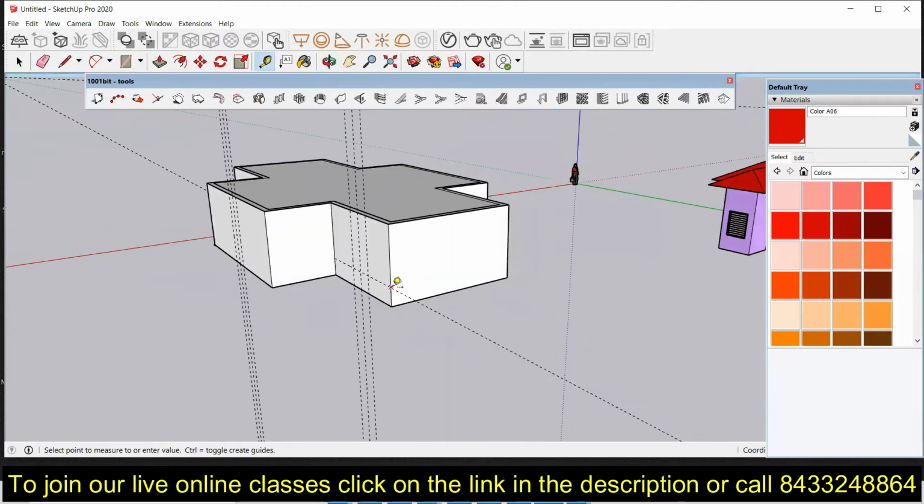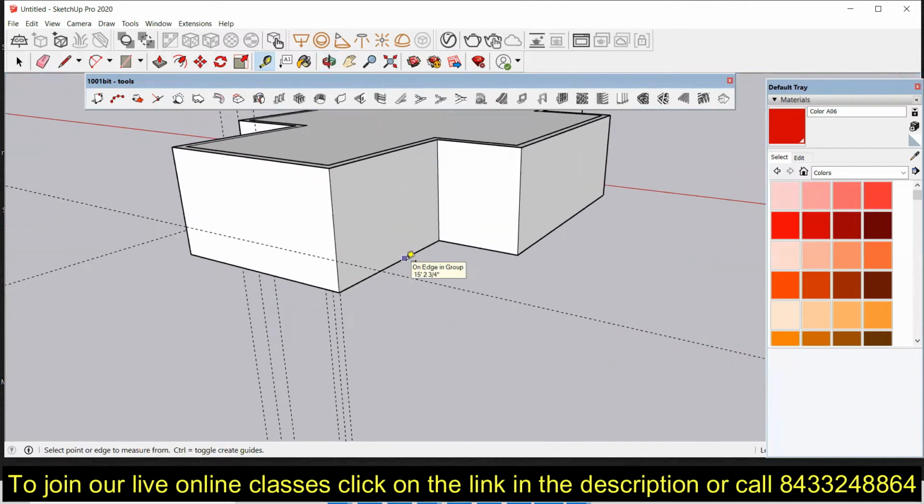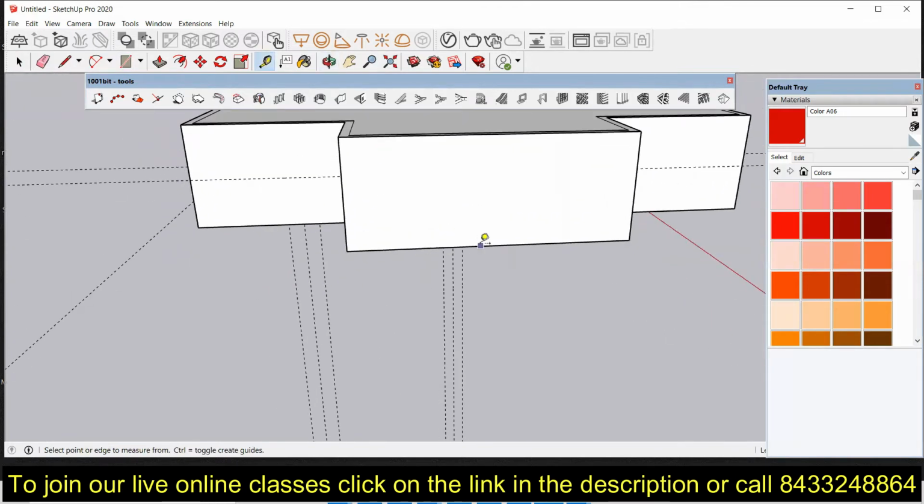We can use the same for here, and for that I don't need to take the distance because I can use the reference line easily. Now suppose you want to make a ventilator, then what you are going to do is make the lintel level at 5 feet, sorry, the sill level at 5 feet and the lintel level at 7 feet. Okay, so this way you can also draw a ventilator.